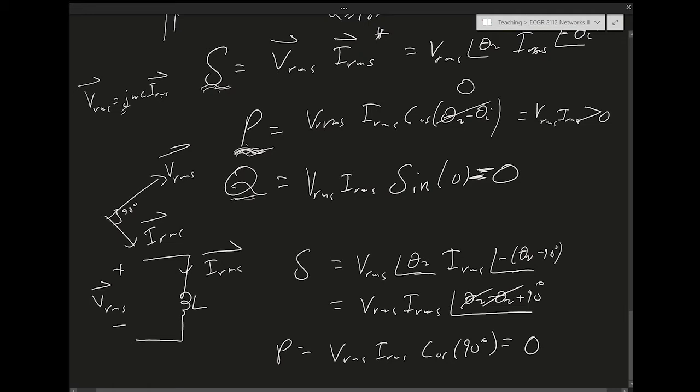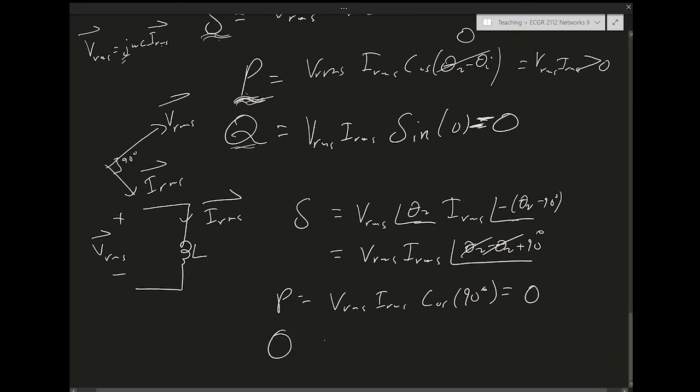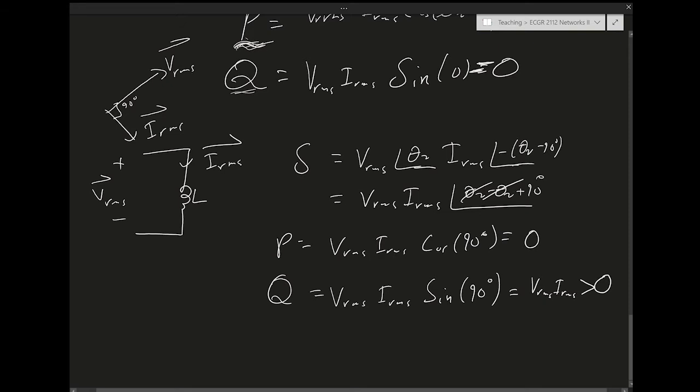So that verifies what we knew already, that the inductor does not absorb any real power. What about the reactive power on an inductor? So the reactive power is going to be V RMS, I RMS, sine 90 degrees. What's sine 90 degrees? 1, right? So this is going to be V RMS, I RMS, larger than 0. So the inductor, in this case,